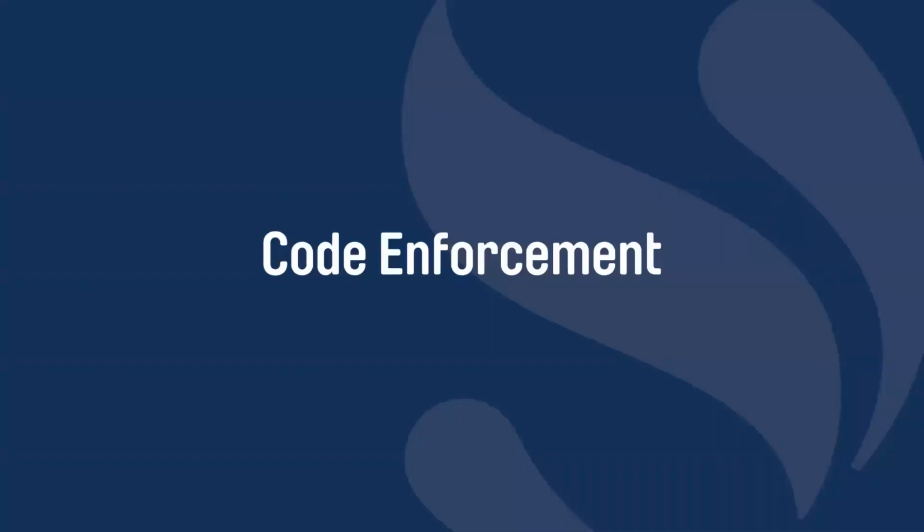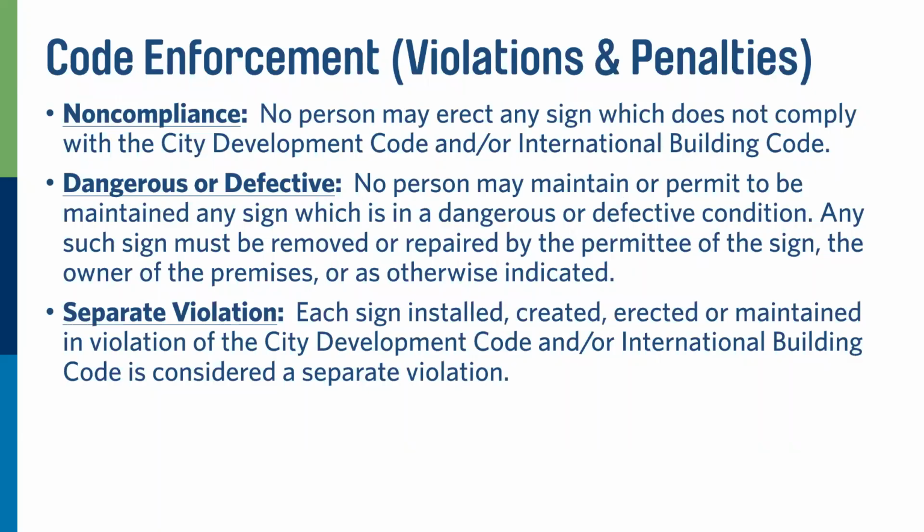Code enforcement. What is code enforcement? This is the violations and the penalties. This is what happens if you don't do it right. All right, non-compliance. Non-compliance is where no person can erect any sign which does not comply with the development code and the building code. So if you don't meet everything we talked about today, you're in trouble, especially if you went ahead and built it. Existing signs, they'll be grandfathered in. Like if they were already there before the city or whatever, you'll be grandfathered in. But any new sign or replacement sign has to meet all this criteria.